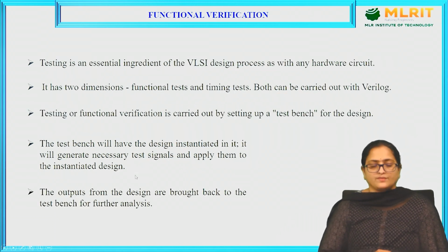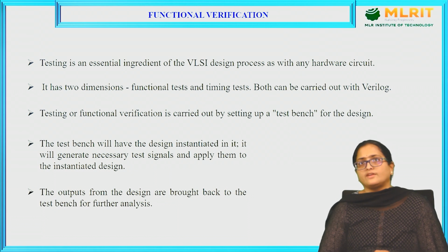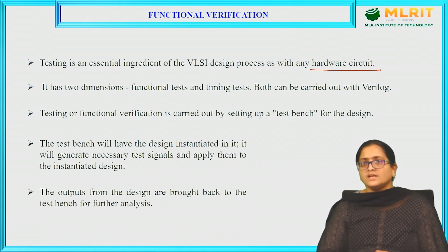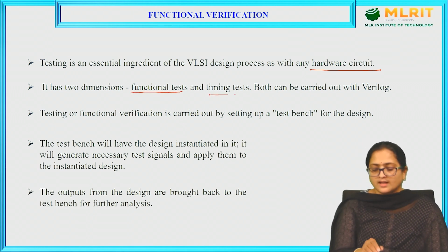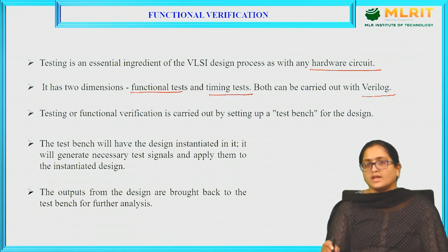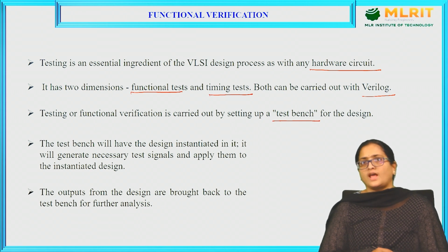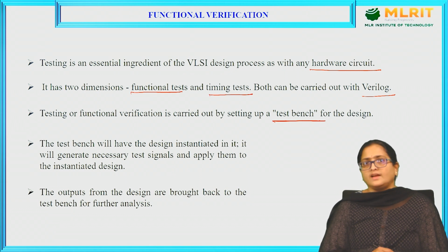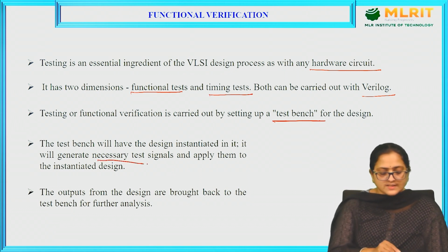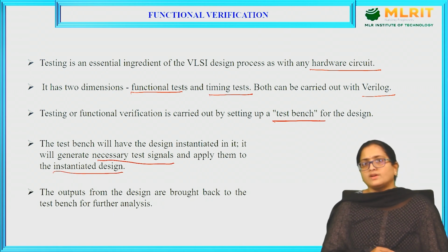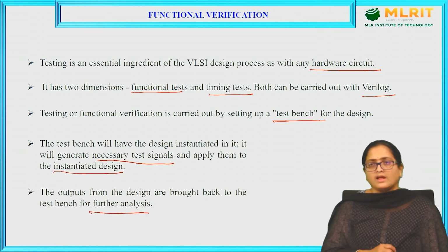Next one, functional verification. Testing is an essential ingredient in the VLSI process with any hardware circuit. It has two dimensions, the functional test and the timing test. Both can be carried out in Verilog. Functional verification is carried out by setting up a test bench for the design. The test bench will have the design instantiated in it. It will generate the necessary test signals and apply them to the instantiated design. The outputs from the design are brought back to the test bench for further analysis.